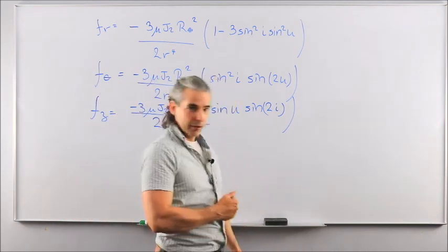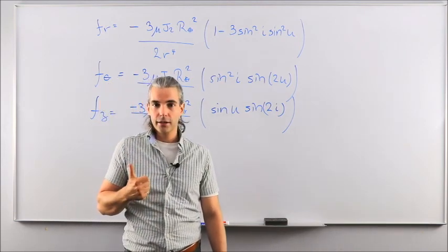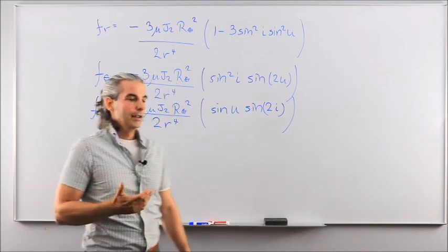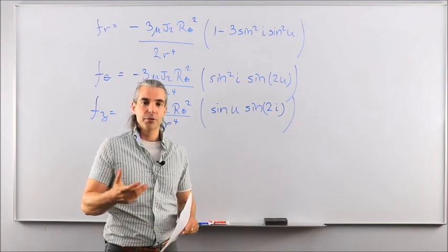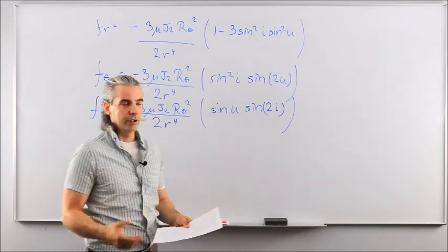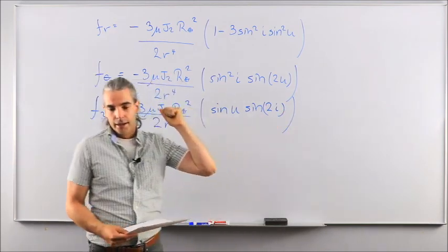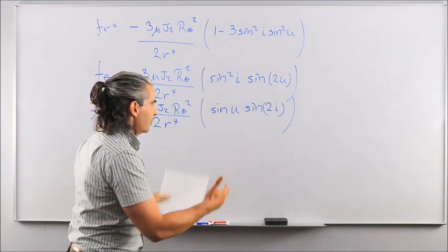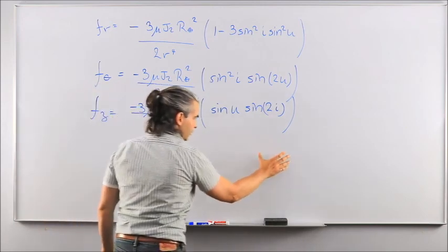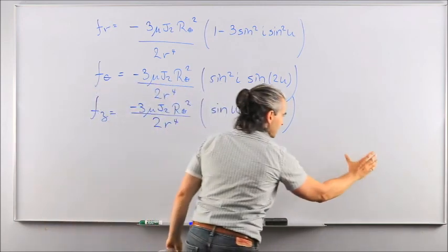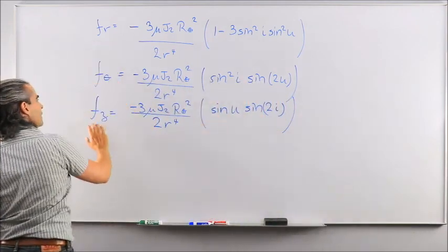Then we took the gradient of that to get the inertial acceleration due to this perturbing factor, J2. But we said, oh, that's not good enough, because what we want is FR, F theta, and Fz, and thus we looked at the inertial version of it in terms of vectorial equation and expressed all vectors in the orbital reference frame, played with the equation such that we ended up with one scalar multiplying OX, another scalar multiplying OY, and another scalar component multiplying OZ, and we called those FR, F theta, and Fz, obviously.